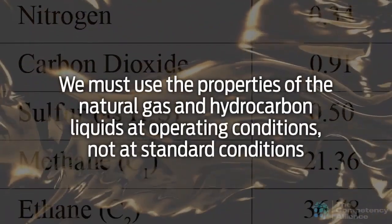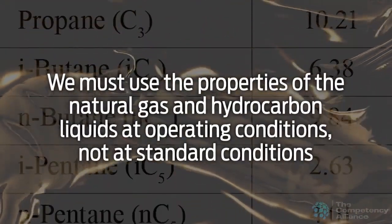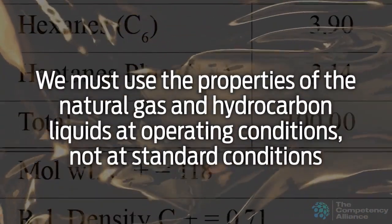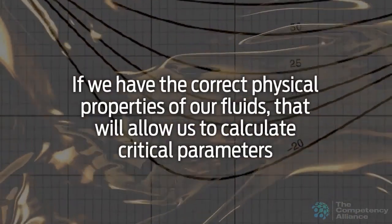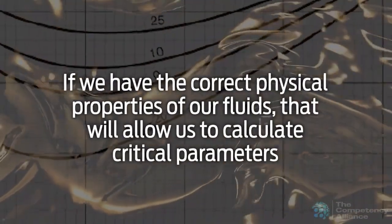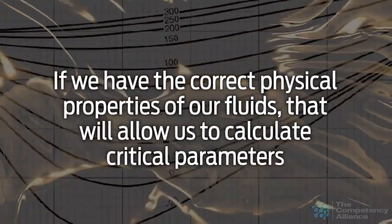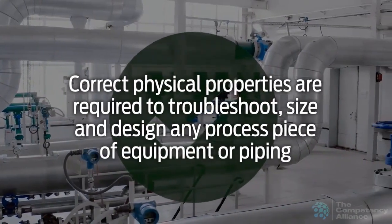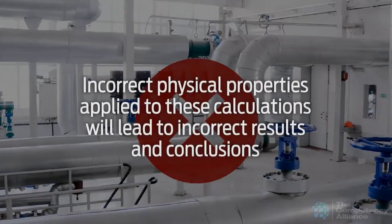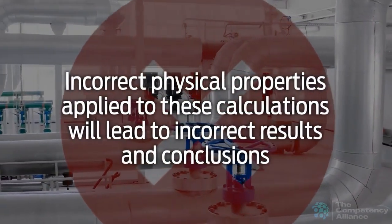We must use the properties of the natural gas and hydrocarbon liquids at operating conditions, not at standard conditions, as nearly all of the processes in our facilities are operating at elevated pressures. If we have the correct physical properties of our fluids, that will allow us to look inside the pipe or equipment and calculate critical parameters, such as fluid velocity, actual volumetric flow rate, etc. Correct physical properties are required to troubleshoot, size, and design any process equipment or piping. Incorrect physical properties applied to these calculations will lead to incorrect results and conclusions.